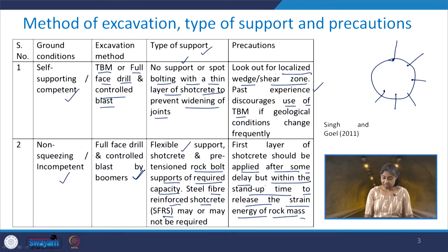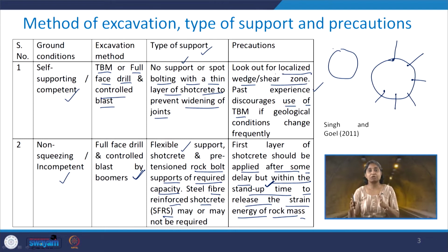Now, there is another term which we have not discussed till now, the stand up time. Say you have excavated the ground. The stand up time is the time between the excavation and the support installation, such that this excavated portion can stand on its own.